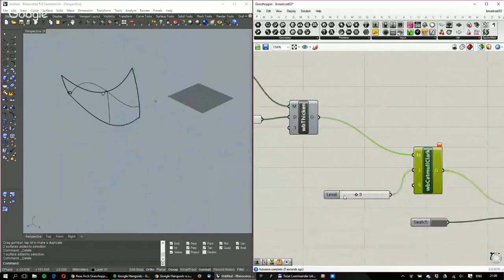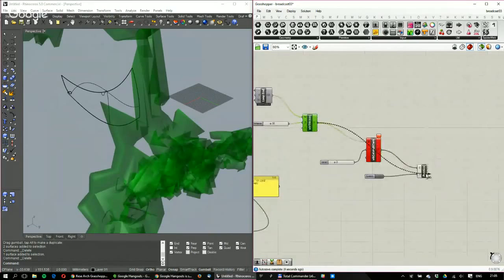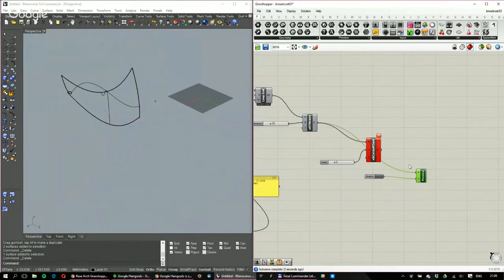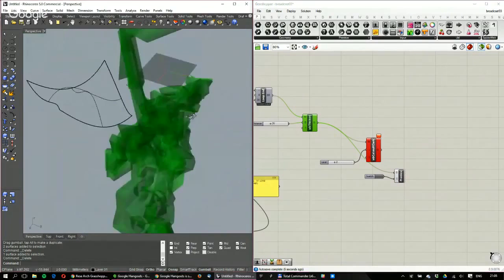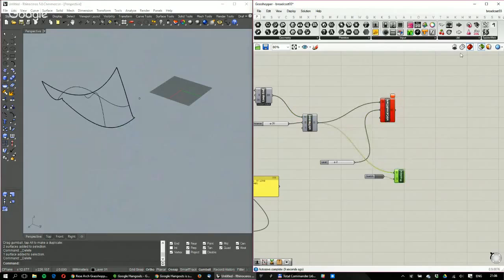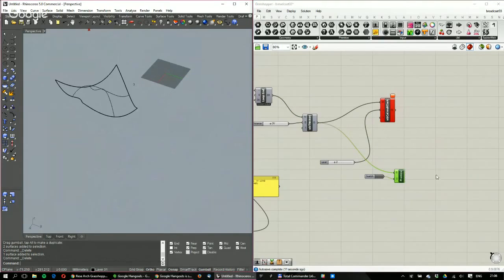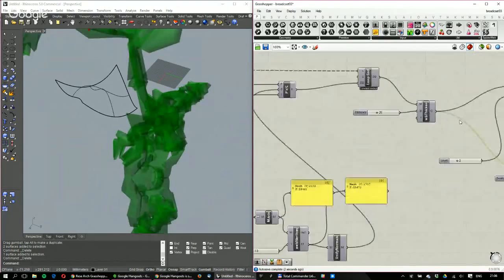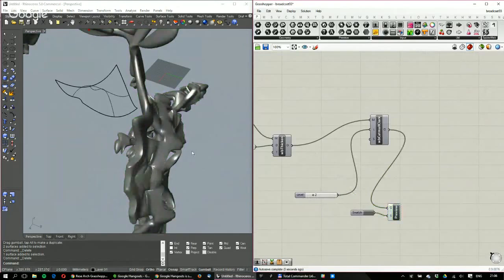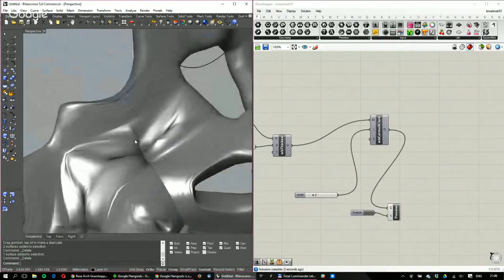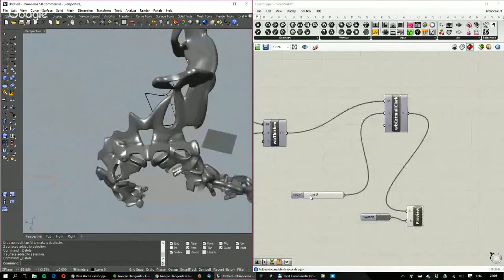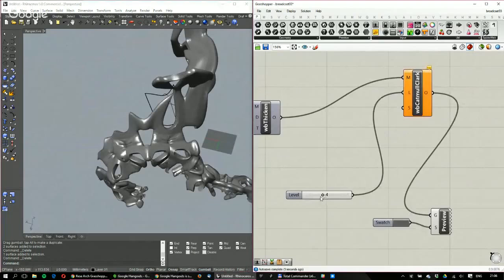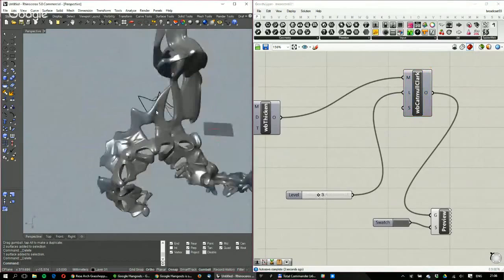The problem is that this Weaverbird Catmull-Clark is very picky, and it only accepts nice, good geometry, and this one is certainly not that for some reason. And for some reason, it cannot even be displayed. So maybe welding them too much is not a good idea, but now it seems to work. Welding too many points together probably breaks the geometry, but I don't know.